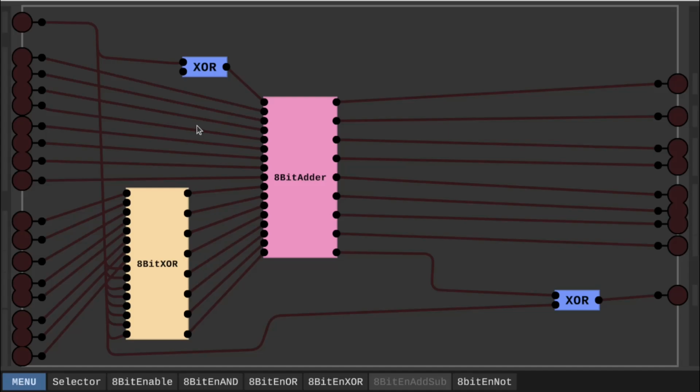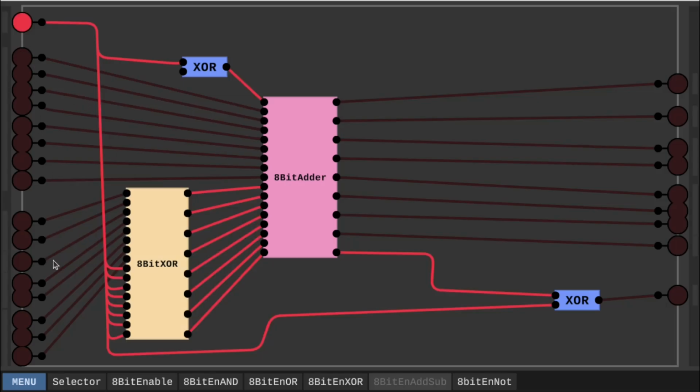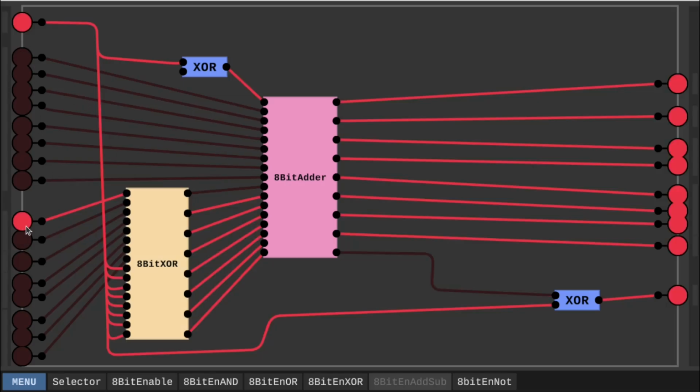As I lost some data, here's me trying to give a brief explanation. I created an adding and subtracting system, so if you press the subtract button, it will allow you to go into subtract mode, and the second argument will be subtracted from the first. The way it does it is by using a little system called 2's complement. And to do that, you invert the data that you're doing and add 1. And by adding 1, we can do that. With that, we can do other things. So here's me showing that, hey, 0 minus 1 is -1, and there's a little carry because it thinks it's a big number.